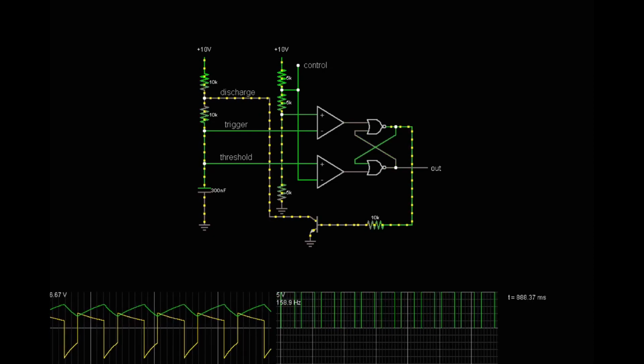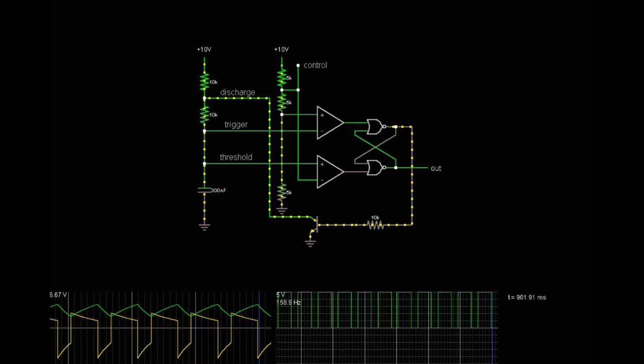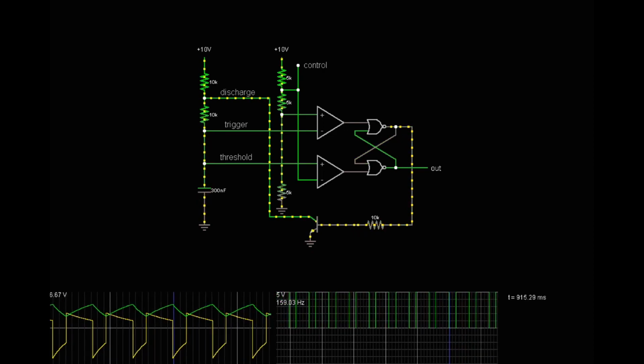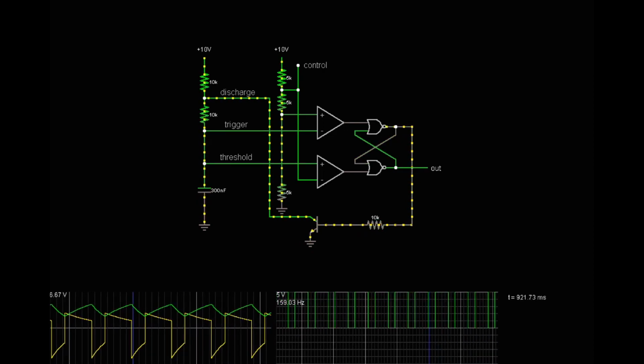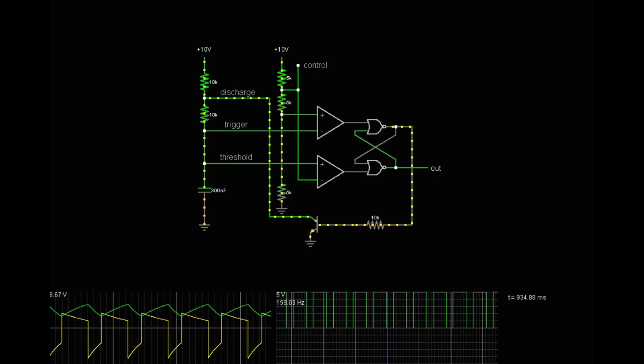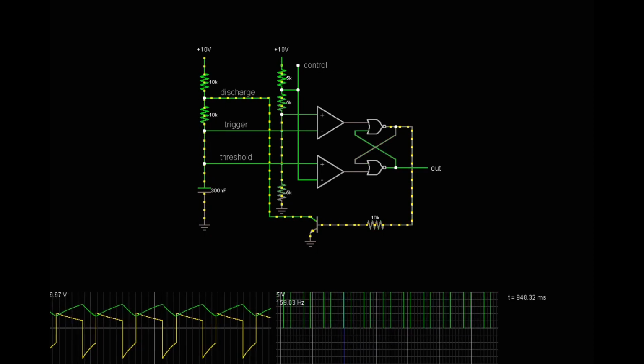8. VCC power. Positive supply. For bipolar timers, the supply voltage range is typically 4.5 to 16 volts. For CMOS timers, the supply voltage range is typically 2 to 15 volts. Decoupling capacitors are generally applied between this pin and GND as a good practice.